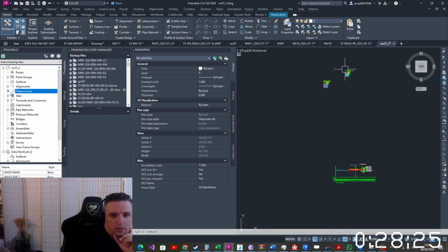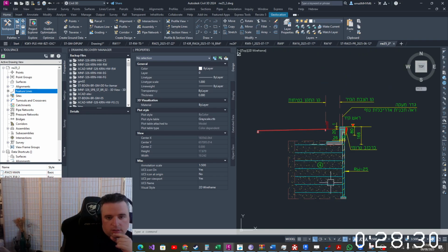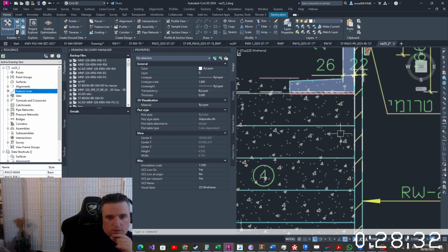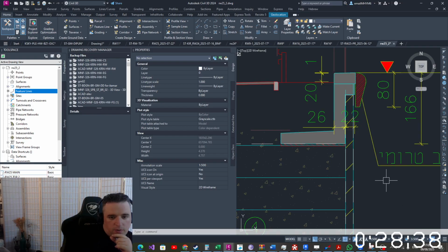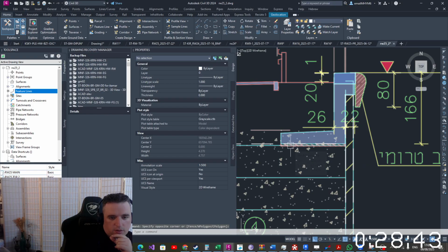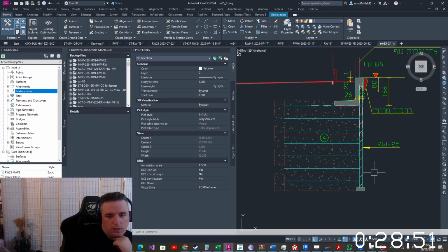Now what we need is to first create the reinforced earth section. So we'll start by this wall, and we'll have the blinding concrete here, the wall, and the parapet in the same family, the cast in place parapet. And we'll have a length parameter that will control the visibility. Okay.